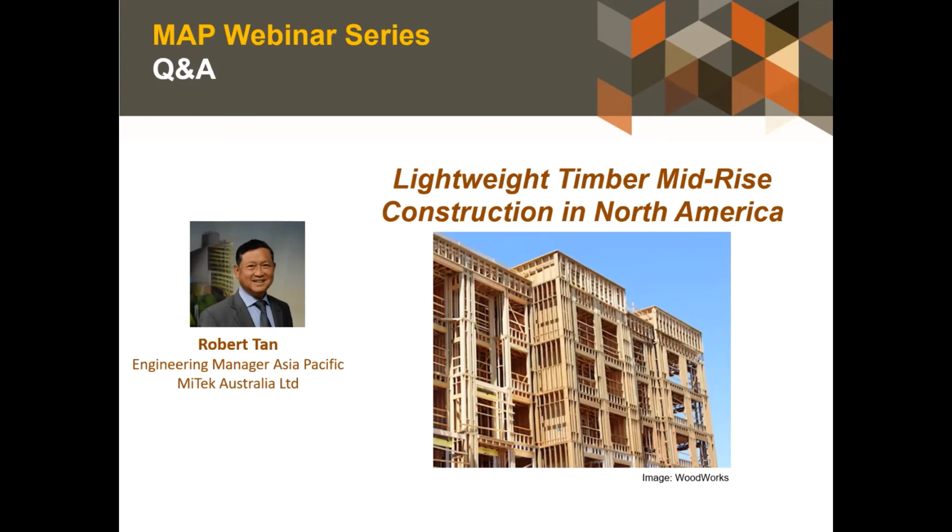And then compression. Obviously, as you press down on all the beams and blocks and studs, everything does come down and will move. But a lot of it actually happens early, and the later movement would be when you start moving in furnishing and other things and start loading the live load and so on. The fourth one I didn't quite mention: as the building shears in wind or moves for whatever reason, of course there'll be an uptake of the movement and the building might come down as things compress. So the key idea is to tie down with a locking system that will continuously lock the building down, so that it doesn't continuously create a slackness in the structure.